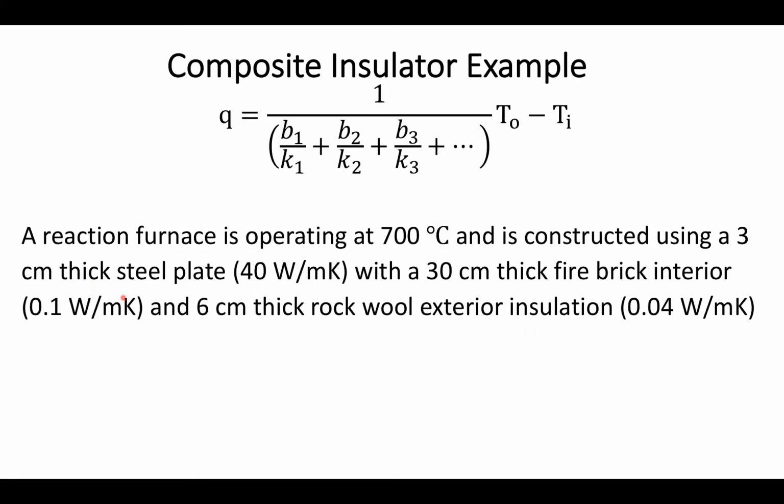So you'll see this in a lot of fireplaces. However, we also need an additional set of insulation because it turns out fire brick is a good insulator, but often not good enough. So you may have a nice layer of rock wool exterior coating the surface. So you'll see this fairly commonly in a lot of fireplaces or kilns.